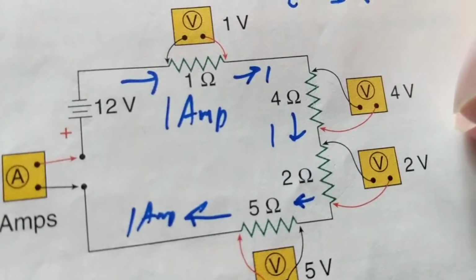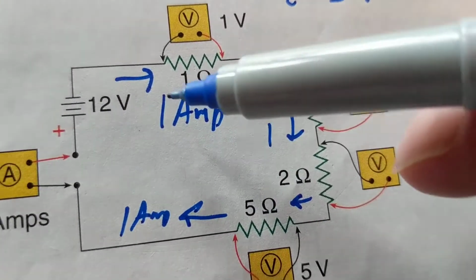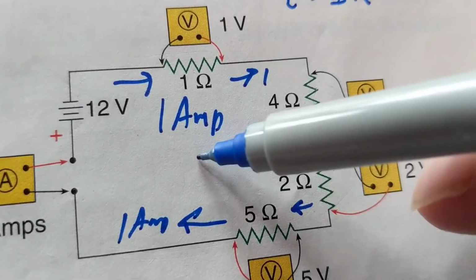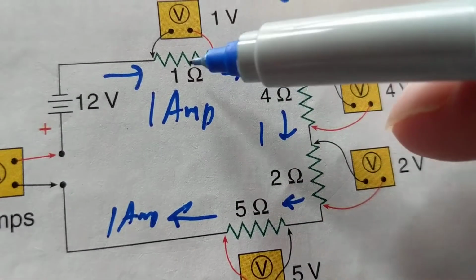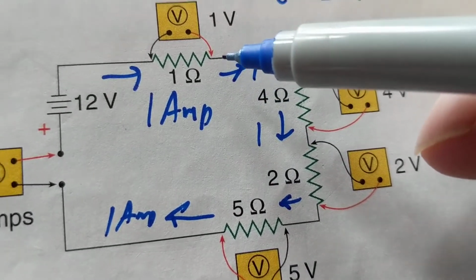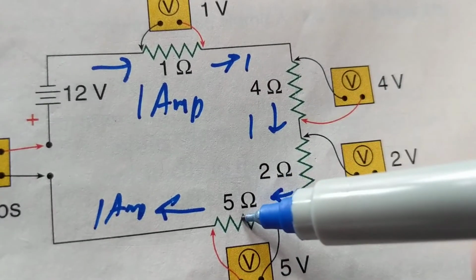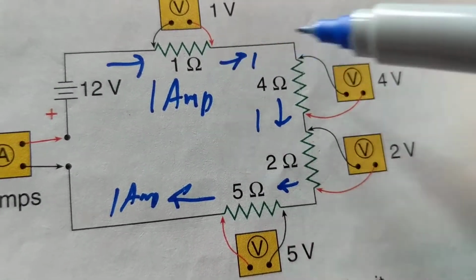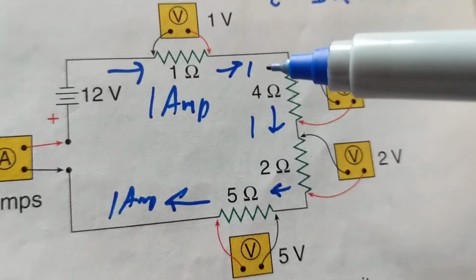Now, let's go with a short. And this was where the confusion was. If these are 4 bulbs in series, obviously, let's say each resistor represents the resistance of each bulb's filament inside. Let's say I have a short across any single one of these. Do the lights light? And the answer is yes.